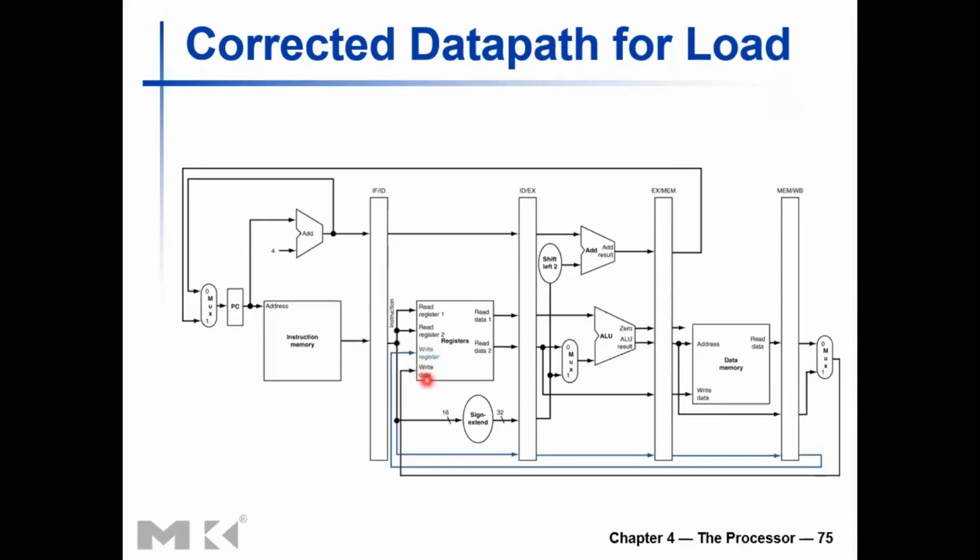You need to hold the data and address table for a little bit of time for the register to capture that value. And from the same rising edge, some later instruction, which was stored in a pipeline register here, will be written to the pipeline register, then read, and the reading will stabilize here. So the reading will stabilize with, if you are reading the same register that some previous instruction is just now writing to,